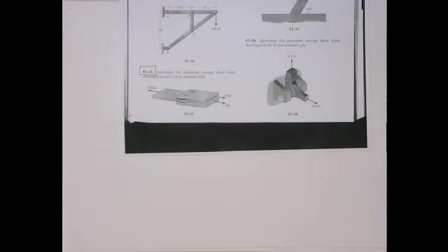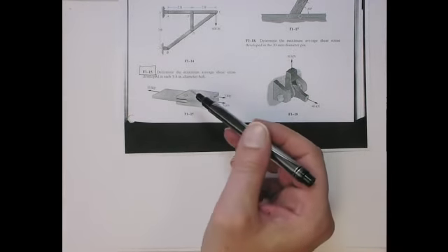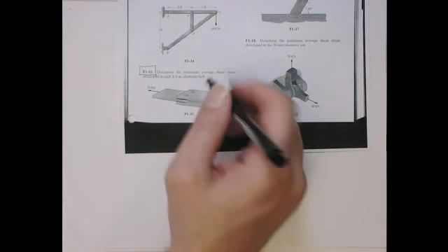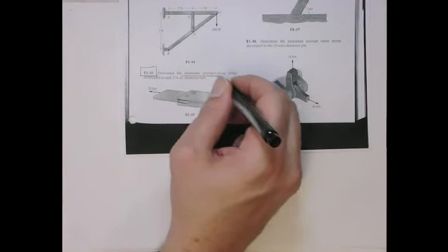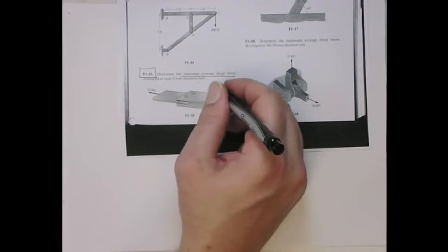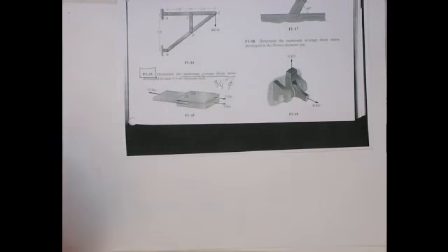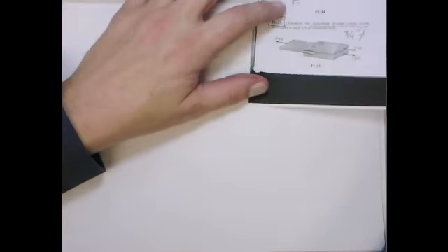Okay? But anyway, the problem here is they give you the forces on the plates and they want you to determine the maximum average shear stress in each of the bolts, and it tells you that each bolt has a 3/4 inch diameter. So we can get the cross-section area. Let me just tuck this up here in the corner so at least you can see the picture.